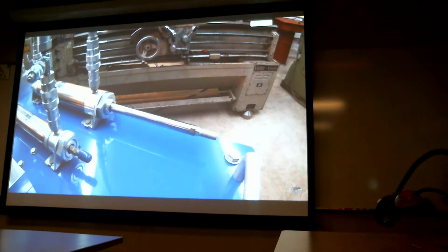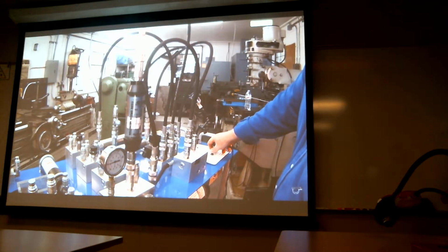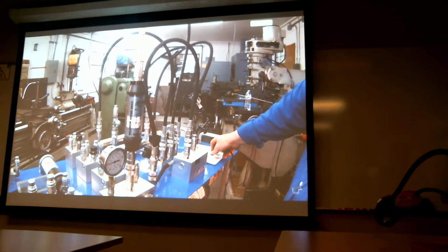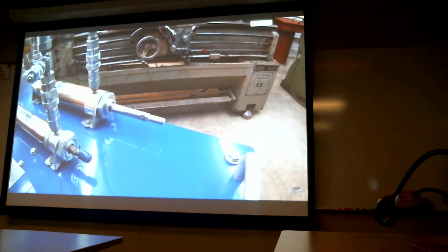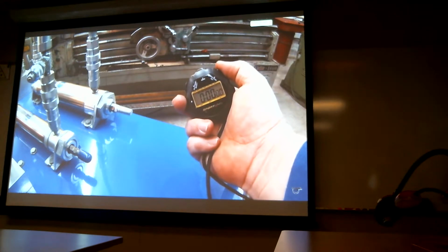So what I'm going to do is cut that down to about half. So a little less than 1 gallon a minute, something like that. And then we're going to time this coming back out, and it should be about half. It may vary just a little bit because the oil is kind of cold, but we'll give it the old college try here.